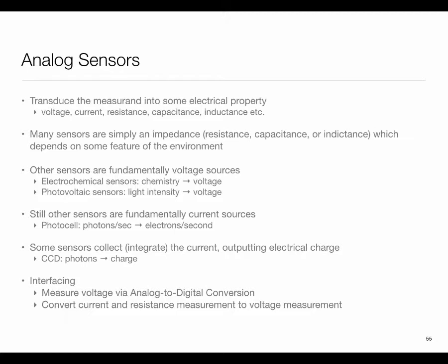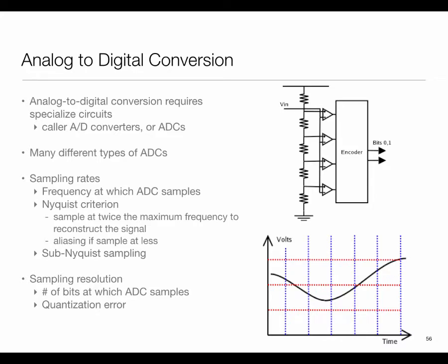If you look at an image sensor, it has a whole bunch of capacitors on it. When light falls, it causes each pixel to charge up differently, and then you read out that charge, digitize it, and that's the image that we get. So what these sensors fundamentally require is measuring voltage or current and doing an analog to digital conversion over that. These are well-known, well-understood things. Still, high speed and low power constraints come in, and a lot of people work on it. It's built into our microcontrollers at this stage. You don't worry about it.